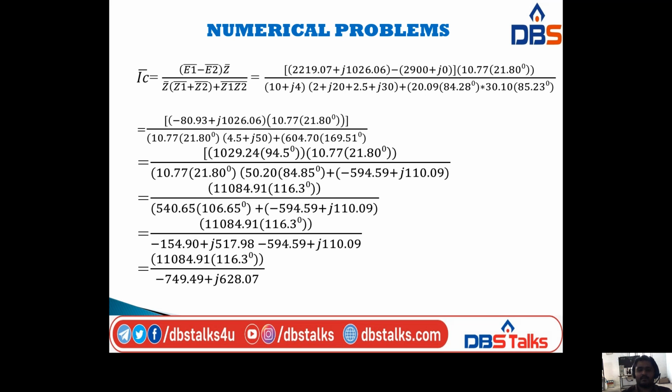And this is the formula to calculate the circulating current. We already derived this formula in the previous sections. IC bar is equal to (E1 bar minus E2 bar) into Z bar, divided by Z bar into (Z1 bar plus Z2 bar) plus Z1 bar into Z2 bar. Please substitute the values given in the problem into this formula.